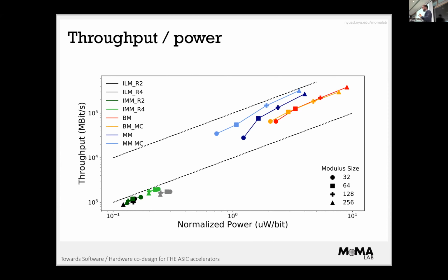Power is one of the two big problems with designing hardware for FHE. One is data movement, the other one is power. Because what we compute on is cryptography. Cryptography has 50% switching, pretty much. So you cannot really have patterns where half of the chip is not used now, and the other half is used. Everything will be used all the time. Having these patterns coming into your chip makes your chip very prone to having hotspots. And having hotspots may eventually lead to higher than expected thermal properties that could lead to damage in silicon. So power has to be taken into consideration very early in the design stage.